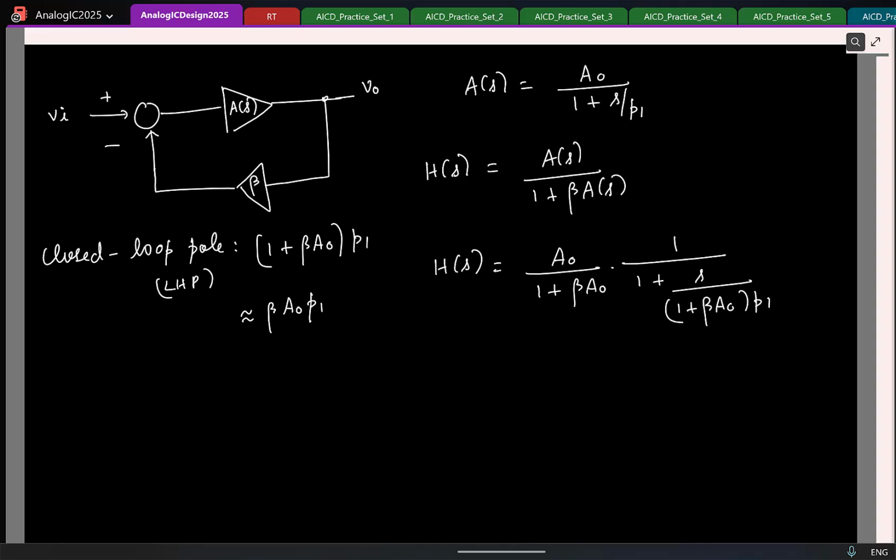No, right? So a first order system, if you put in negative feedback, is guaranteed to be stable. So that is something to have in mind. I'll say first order system in negative feedback is guaranteed to be stable.